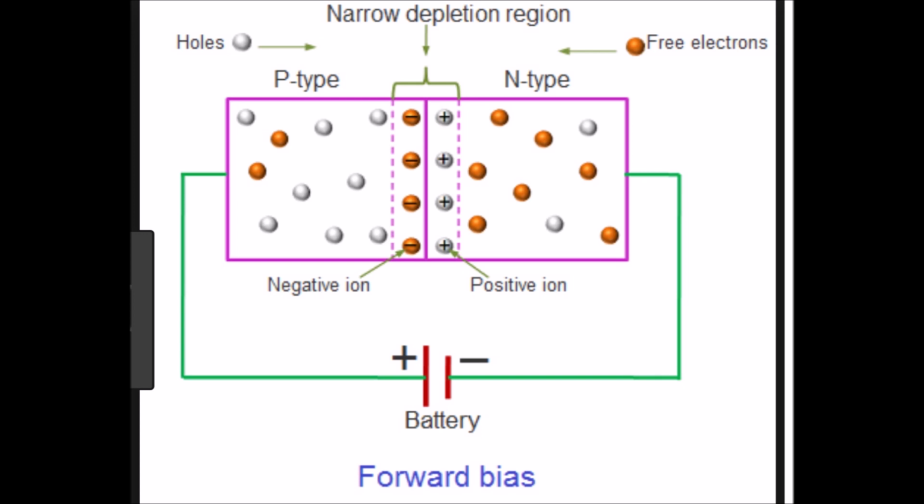Forward bias. The DC voltage required to maintain current flow in a bipolar transistor or diode, or to enhance current flow in a field effect transistor. For example, a silicon diode will conduct current only if its anode is at a positive voltage compared to its cathode. It is then said to be forward biased.